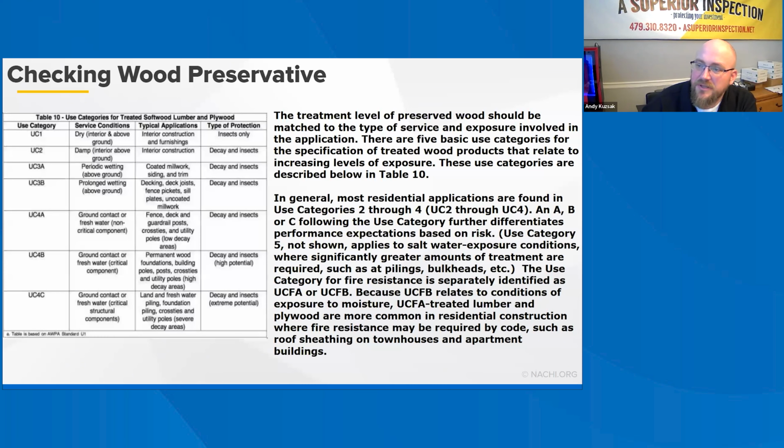Other types of foundation wall construction methods and materials are less frequently used in the United States, including permanent wood foundations, insulated concrete forms, although that's becoming more and more common, precast concrete foundations, which is kind of common in my area, and elevated foundations in flood-prone areas, which is also common in my area.